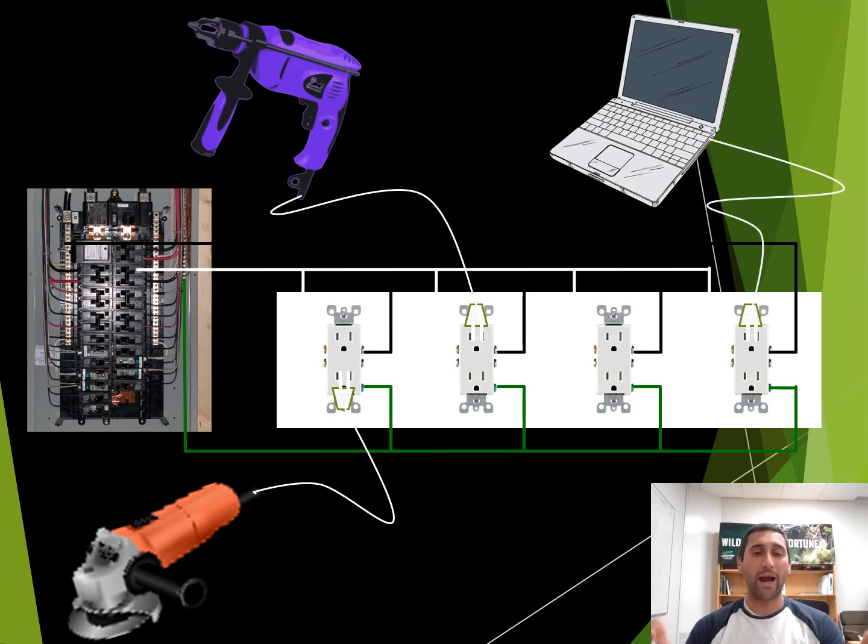So when you are wiring these things, you have to account each one of those receptacles as being 1 amp, so that it can indeed have that protective value on the circuit breaker of 12 amps for a 15 amp breaker. So you'll just plug those things in. It's kind of like opening and closing switches, but at no point will you have a current draw of greater than 12 amps, because if you do, then the breaker will trip. All right, so that's how you account for that.